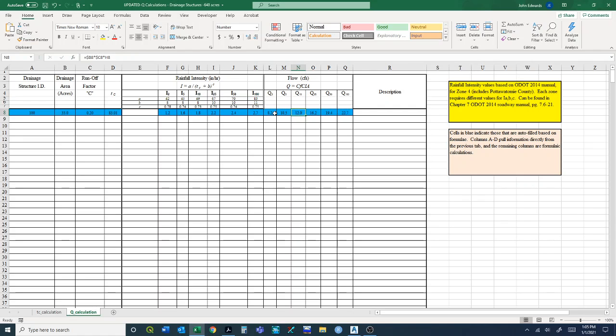within this formula. Remember that the C of F was 1 for everything the 10-year flow and under, so you don't see that calculated in here because it would just equal itself. But once we get to the 25-year, we now have this multiplier, the 1.1. And similarly for the 50 and 100-year, we have that extra value.